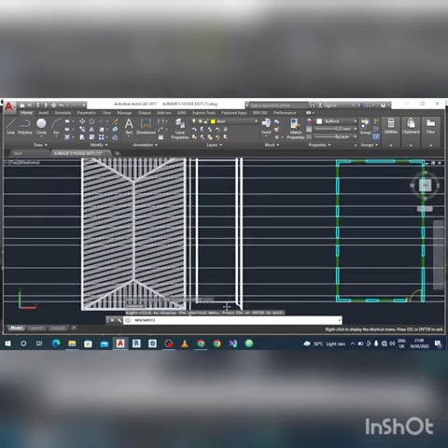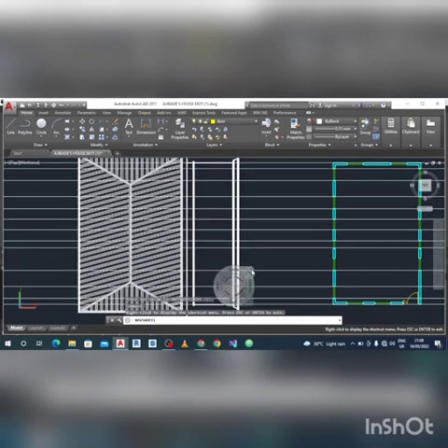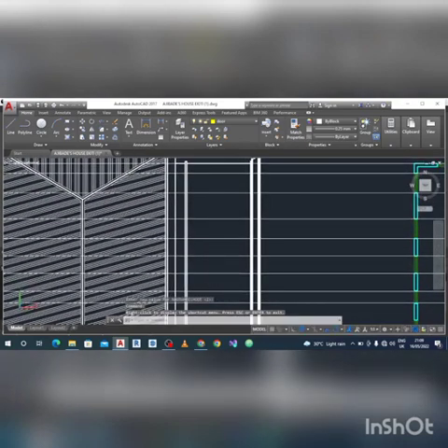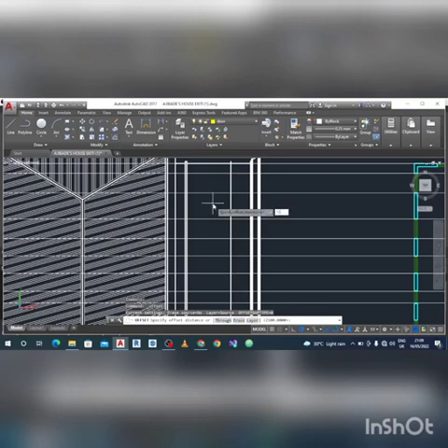So yeah, the same thing we did from the other side. We'll offset the window headroom from the base. Our base is starting from here, so we'll set 2-1. That's 2-1. Enter. That's the height of the lintel. That's the lintel level. Then I'll click on offset again. The window height I'm using is 1-2. Then enter. So I just drag it all the way there.